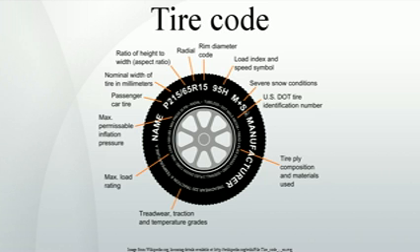The tires on a Hummer H1 might be labeled 37x12.5R17 LT. 37: the tire is 37 in, 940 mm, in diameter. 12.5: the tire has a cross-section of 12.5 in, 320 mm. R: this is a radial tire. 17: this tire fits 17 in, 430 mm, wheels. LT: this is a light truck tire.